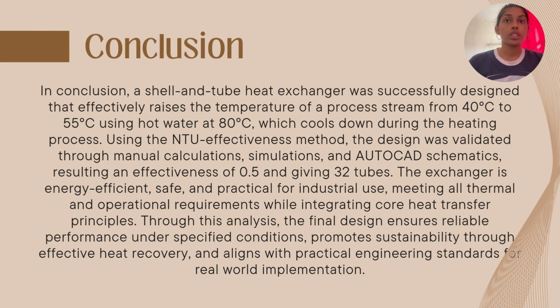In conclusion, a shell and tube exchanger was successfully designed that effectively raises the temperature of a process stream from 40 degrees Celsius to 50 degrees Celsius using hot water at 80 degrees Celsius, which cools down during the heating process. Using the NTU effectiveness method, the design was validated through manual calculation, simulation and AutoCAD schematics, resulting in effectiveness of 0.5 and giving 32 tubes as an end result.